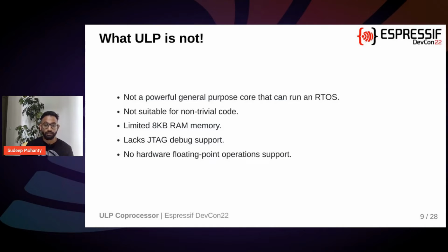There is no JTAG debug support on the ULP core, so the debug ability is a bit limited for the ULP core. And also, there is no hardware floating point operations which are supported on the ULP core. So essentially, the ULP core will be useful for some trivial code which can help your application save power.